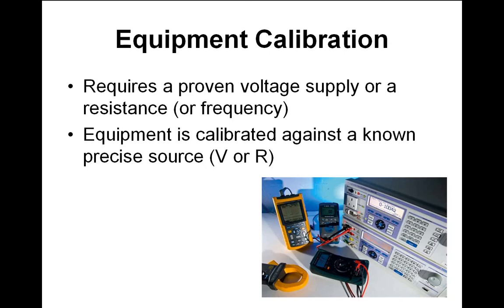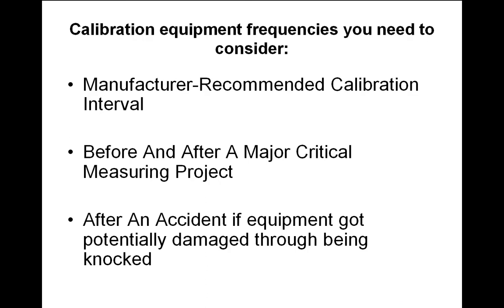Right, next one. Calibration equipment frequencies you need to consider. So frequencies, I don't mean the frequency, but the intervals. Maybe I should use intervals. So very often there's a manufacturer recommended calibration interval for sensitive equipment where it's important that you have your equipment calibrated.